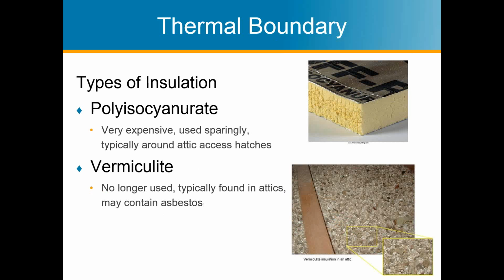And then there's polyisocyanurate, which is that top picture, and it's kind of got the same texture of styrofoam, although it's a little more fragile. It's expensive, but you've got better R per inch value out of it, so that's why it would be used sometimes. Even though it's a little more expensive, it has better R per inch.